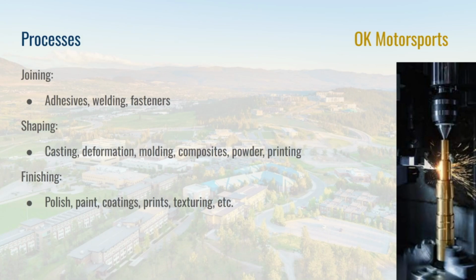Casting, you have a metal, you make it liquid, you put it in the mold, you let it harden, and you get the shape out of it. Molding, similar. I think you mentioned it earlier, injection molding. It's where you can fire hot plastic into a similar kind of mold. It cools really quickly and you pop it out and you get your plastic shape. There's also negative molding, so not negative, it's not called negative molding, but it's the mold of a negative where you take something, you stick it in some kind of medium, that medium assumes its shape.